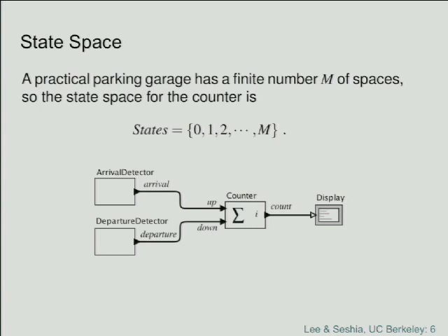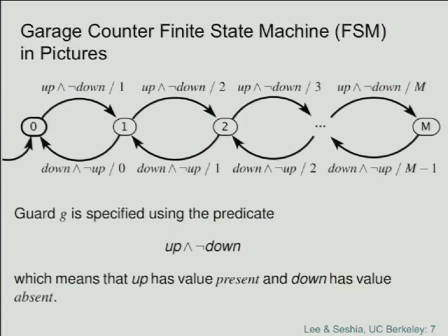Now, because of this state machine design, would it be okay to say, well, the counter just reacts continually. It's always reacting. At all times, guards are being evaluated. Yeah. Yeah, so that could be a poor model from a fidelity perspective. You're pointing out it could be a dangerous assumption that it is continually reacting because that would be hard to implement if you're implementing it in software. And that's true.